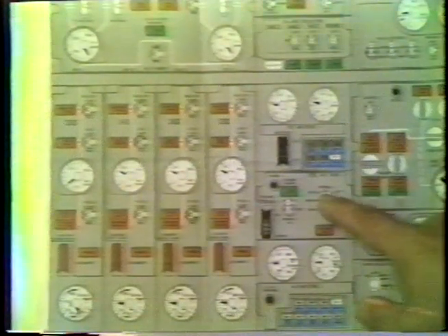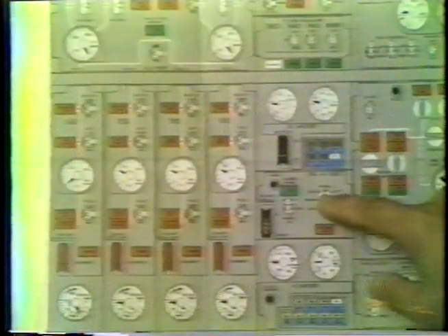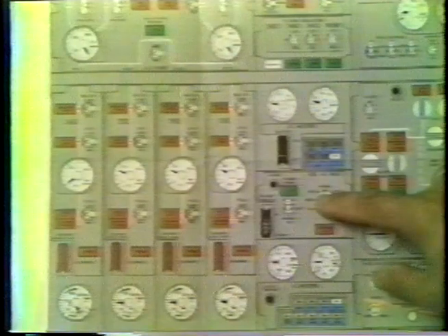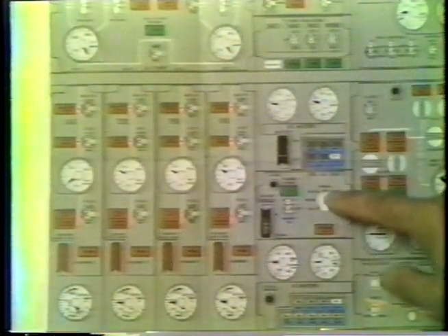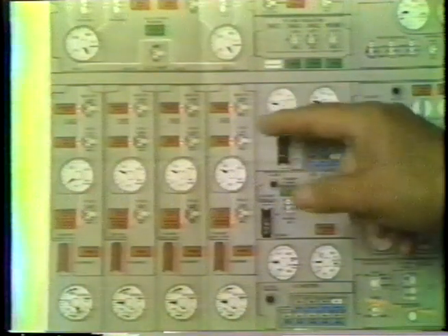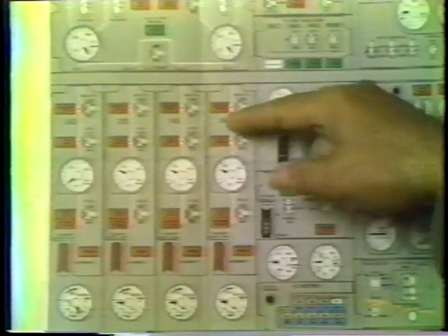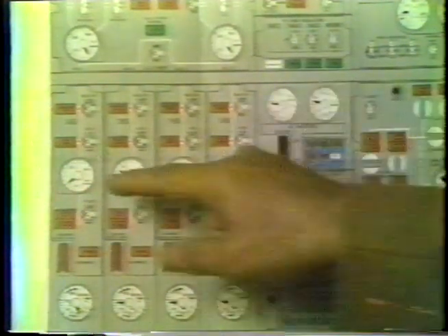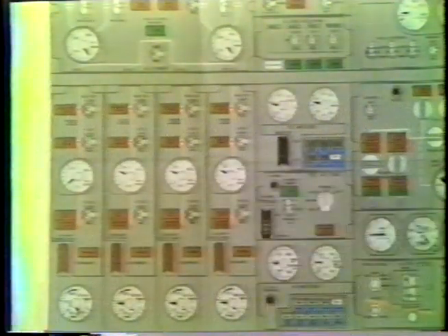Or, if there is a short on the essential bus, it can be selected to off, thereby killing the essential AC bus and not causing a large electrical load on bus number 4 or generators 1, 2, or 3.